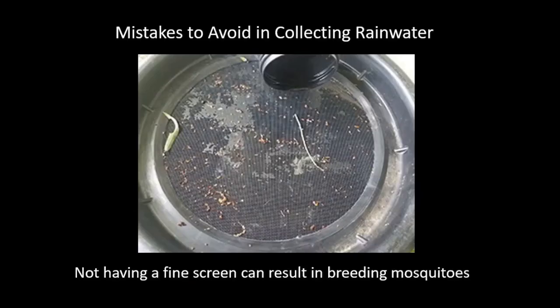One thing is the top of these barrels typically will have a screen, or they should, where the water goes in to collect debris and things, but make sure that your screen has holes small enough that mosquitoes can't get through, because if a mosquito can get in there, then they will love that pool of water to lay their eggs and have more mosquitoes, and you and your neighbors aren't going to like all the mosquitoes you'd have, and you wouldn't realize it's because of the rainwater barrel.